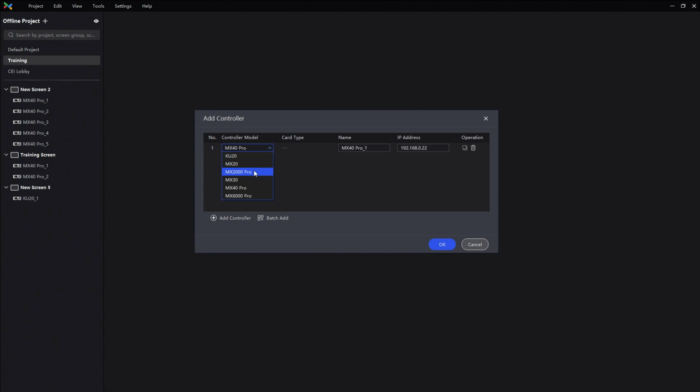To give you an idea, because people always talk about pixel capacity, the MX6000 has 8 output cards. Each output card has 4 SFP slots. Each SFP slot is 10 data ports. So that equates to 320 output data ports, or in pixels, 208 million pixels. Wow. Okay. So we're not even in megapixels anymore. We're in hundreds of millions of pixels. Whole lots of pixels.